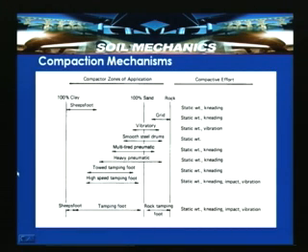As you see in this chart, compactor zones of application and compactive efforts. For clay soils, a type of roller called a sheep's foot roller is used, and for 100% sand or clean sand, the compaction equipment changes almost to the vibratory type. For rocky type soils in rock filled dams, the grid roller has to be used.